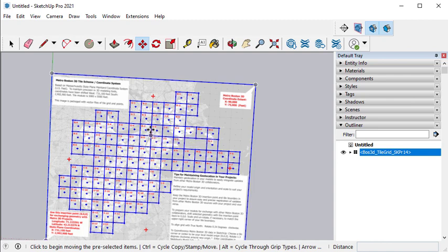The trick I'm about to show you is how to use your own project coordinate system, but retain this tile grid and this insertion point in your model so that you're able to communicate easily, to download updates, to upload updates in the original coordinate system.